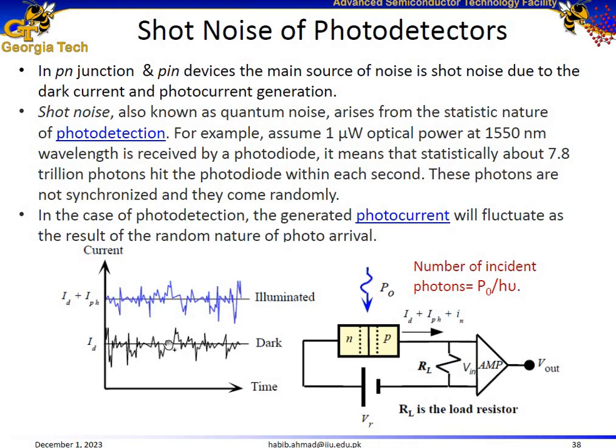If you look at the leakage current of a diode or a photodetector under dark conditions, under a microscope, you would see variations around the mean level of this current. It's not at a constant level. There are certain variations. It has a statistical nature. Similarly, the noise related to the photocurrent also has a statistical nature,